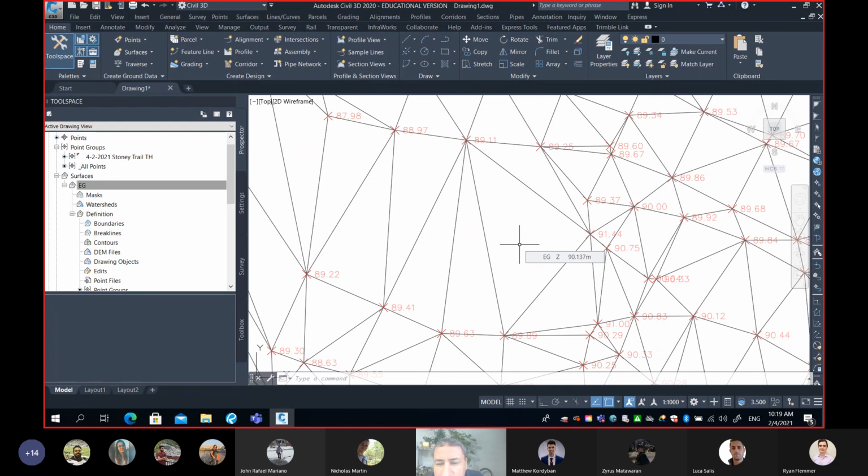If you take a look at this triangle, it has three nodes, 89.11, 91.44 and 89.89. The number the software interpolated is always somewhere in between the three numbers, because it assumes a three-dimensional flat-faced triangle between the 3 points.